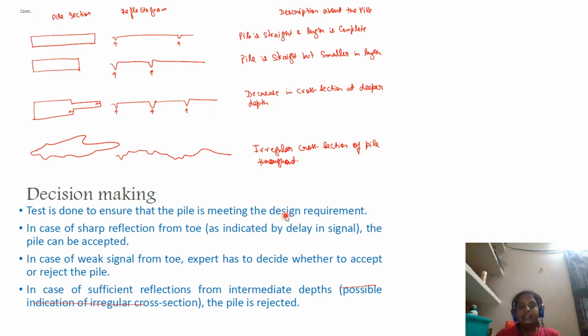So this pile integrity test will help you know whether the formation of that concrete pile is intact, and whether it is formed for the required length, and in a proper diameter, etc. So we are going to test, it is kind of a trial and error. If it's not properly formed, then we have to see what the issue is, or we have to go for a redesign, such things. Or it is about the soil, or it is about the improper workability of the concrete also. If the quality of the concrete is poor, that can also cause issues to the formation of your pile.